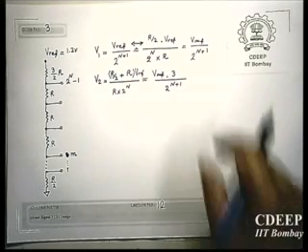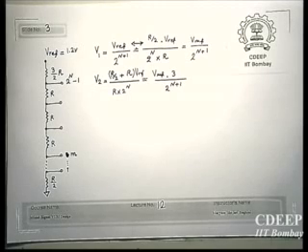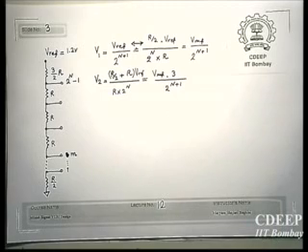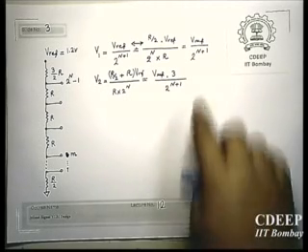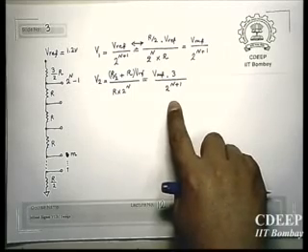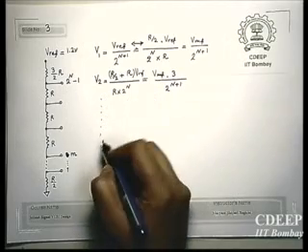And so on. As you notice, the difference between these two consecutive values is 1 LSB. This is the second reference value, which is the transition point. Okay, so these are transition points and we had middle points. So if you remember, we shifted everything by half of LSB. That's why you will see here it is half of LSB, then it is 1 LSB plus half of LSB and so on. Okay, so finally you will reach the final value.